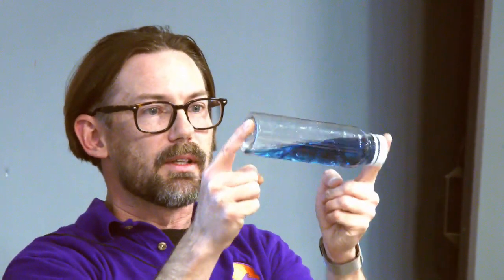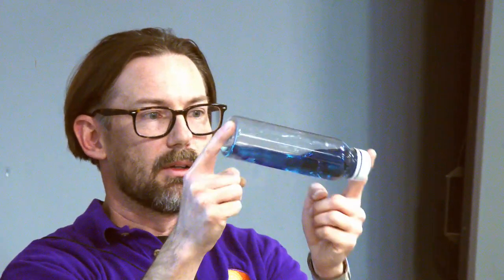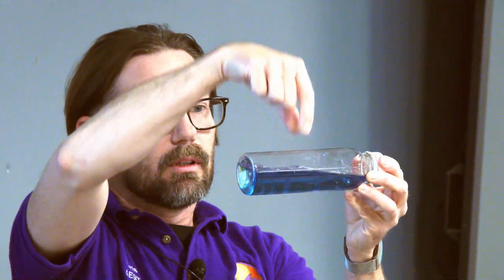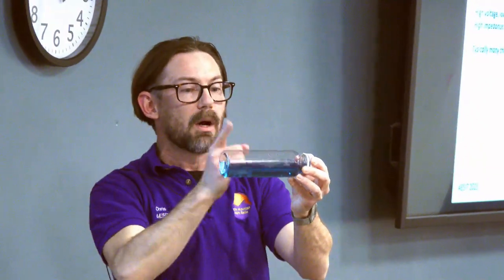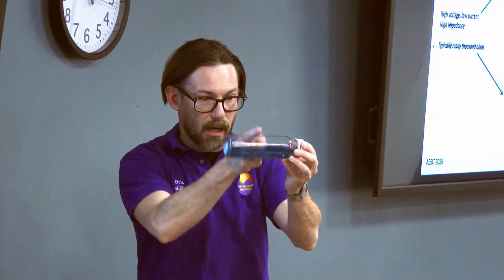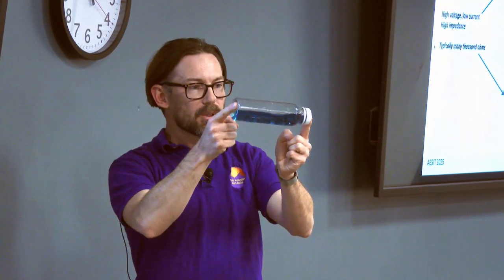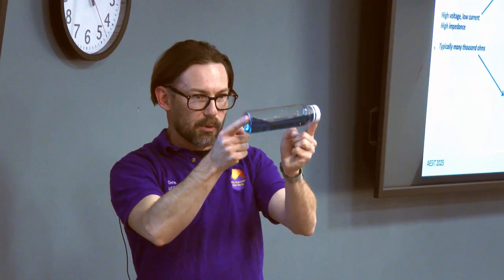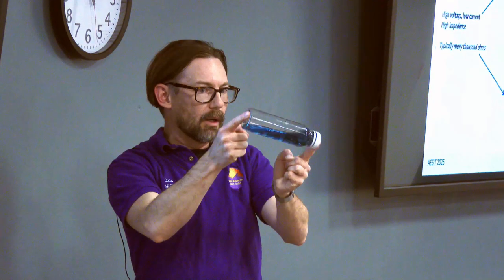So think about the different points on this antenna, the different places in this bottle. Here in the middle, you've got a lot of water sloshing back and forth past you as it goes back and forth. That's a current maximum. You have a lot of water going back and forth at this spot. At the ends, well, theoretically, there's a water molecule on each end of this thing that never moves, right? There's no current on the ends. There's nowhere for the current to go.